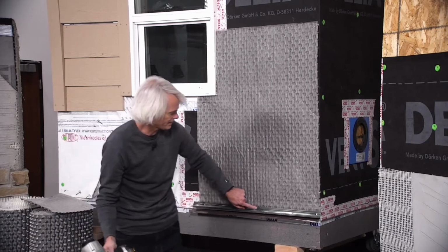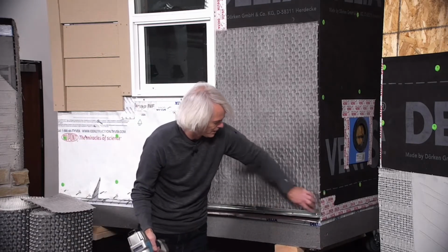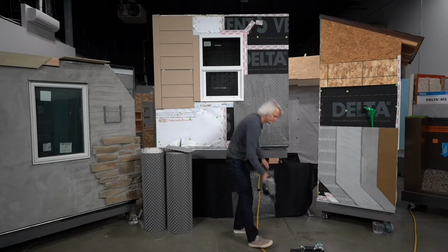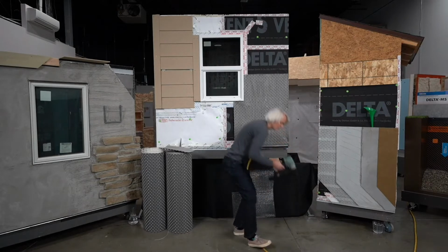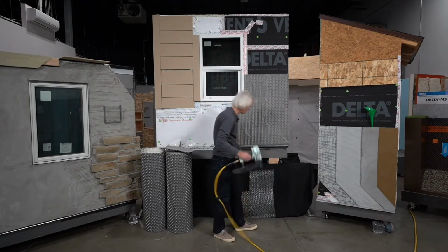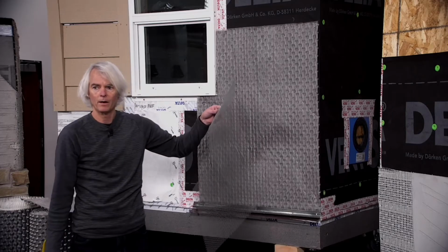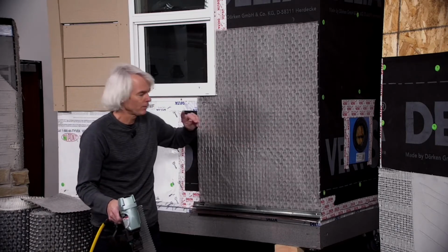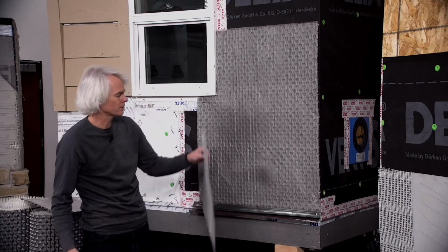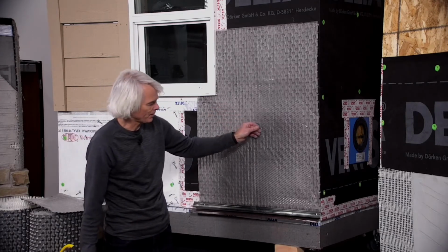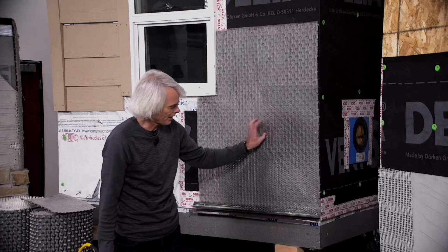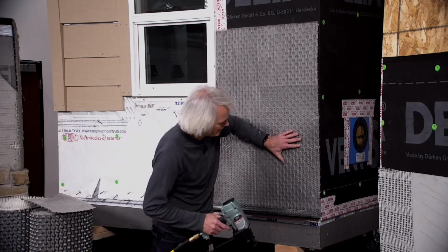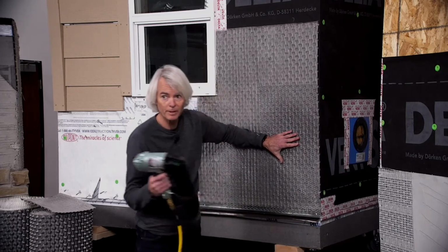And you can see that it dents it in a little, but it's hardly even pushed in that rain screen product. So now we change gun again, and now we're ready essentially to install our lath. This particular product has a receiver sheet on it. We'll talk about the variations here shortly as we go on. My weep screed goes on the front, and here now my expanded metal lath lines up and is put into place. And all we have to do is then, this will be a few more staples.